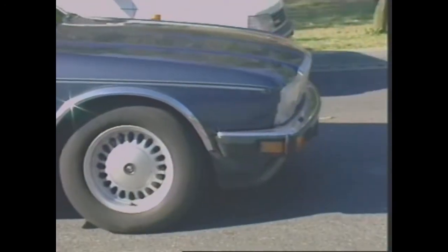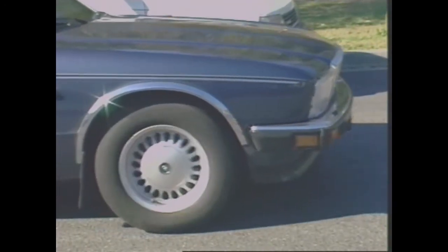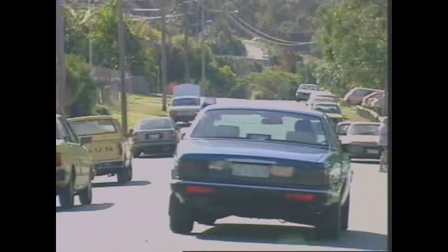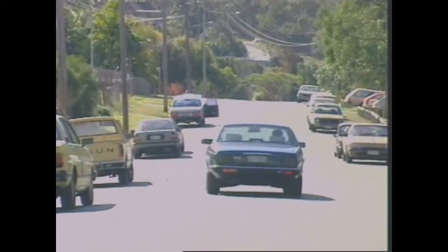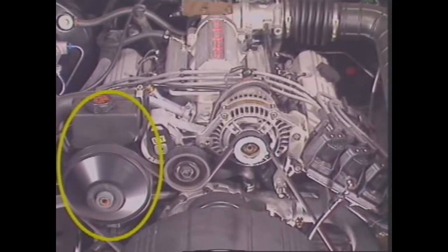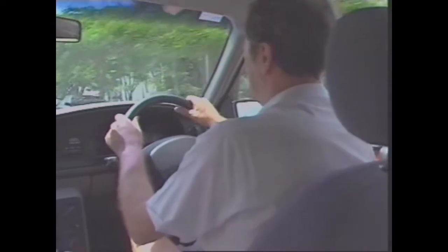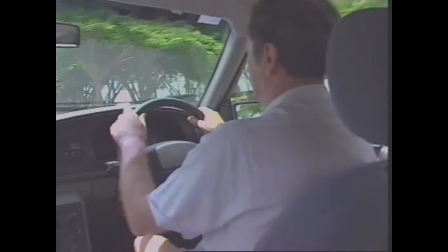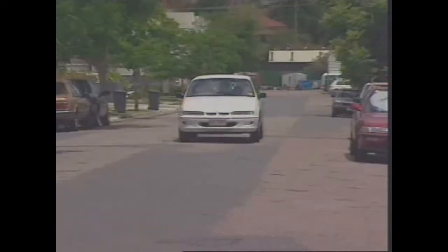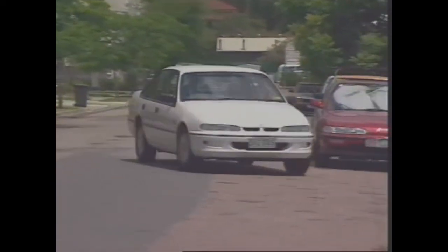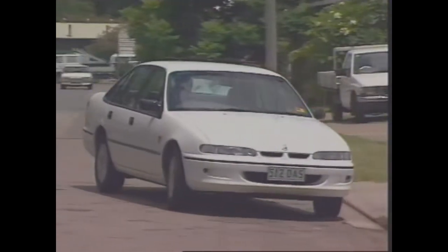With heavier vehicles, increased use of front-wheel drive and wider low-profile tires, more steering effort is needed, so power steering is used. An engine-driven hydraulic pump provides pressure that helps the driver steer the vehicle. The power steering system is designed so that the vehicle can still be controlled, even if the engine or the power steering system fails.